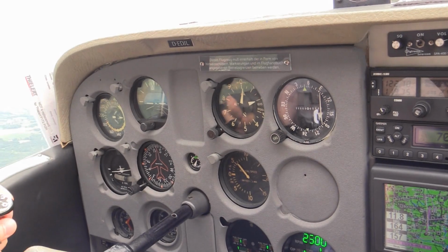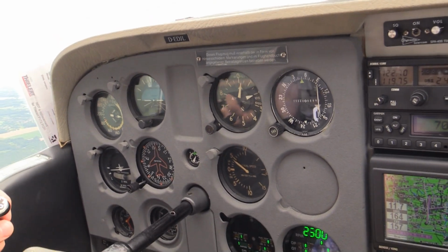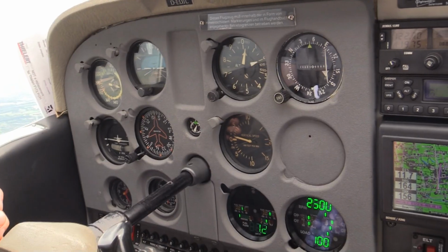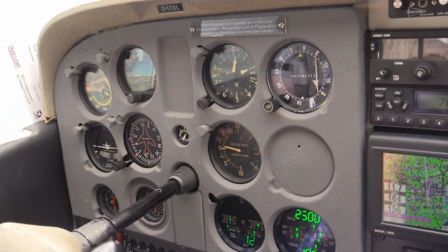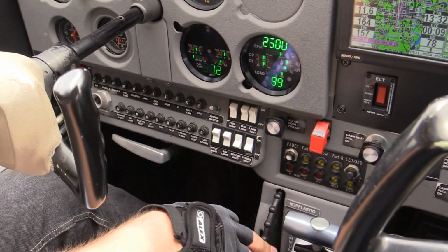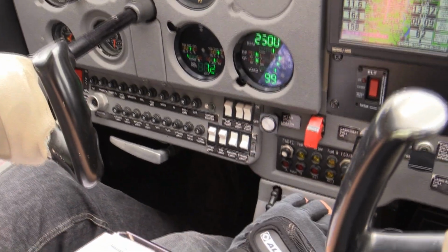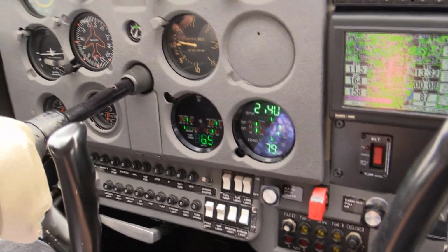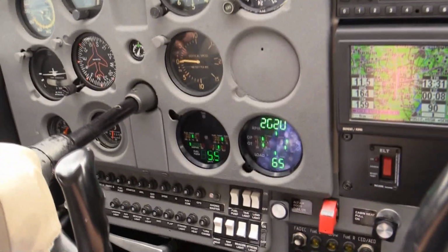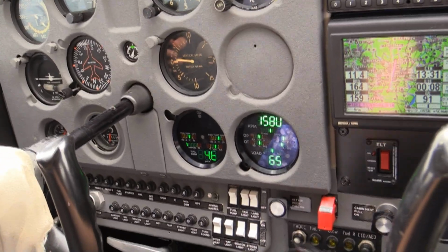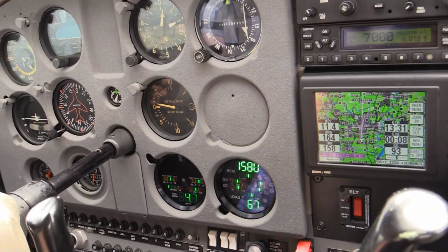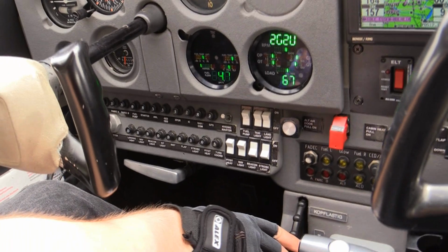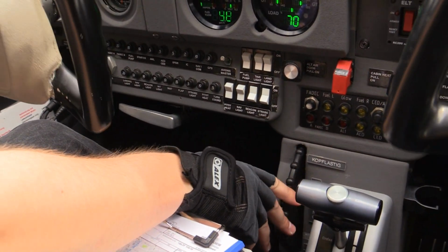Alright, we reached our cruising altitude of 2,000 feet now. Now we're going for a straight and level flight. We're going to trim out the aircraft. And then reduce power to cruise power, which is approximately at 67%. So we got it set here. And now trim out the rest of the control forces. And we're in a good steady cruise towards Essen.